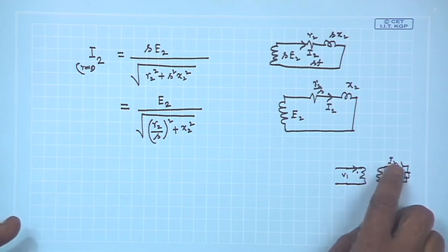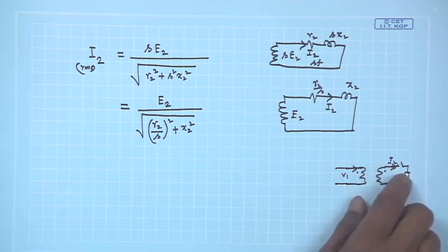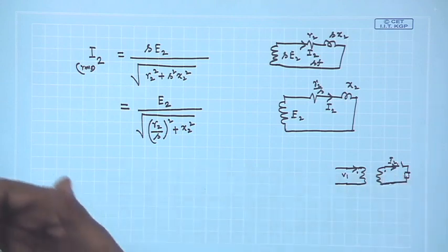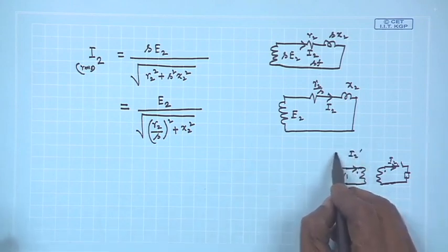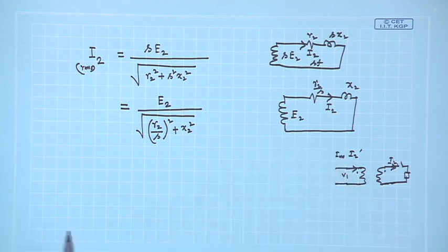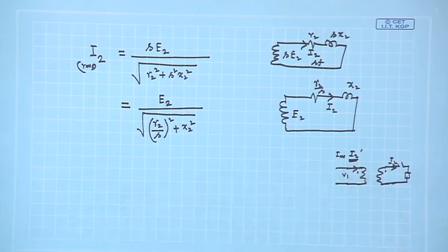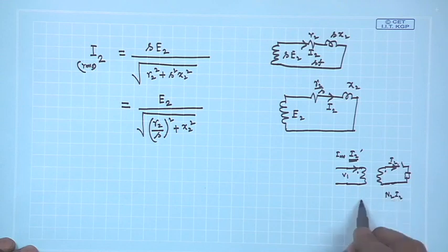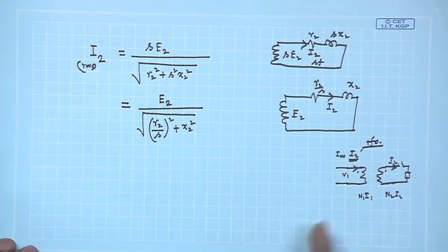Therefore, the extra MMF which is now brought into this system, because you have connected a load on the secondary side, the primary cannot but draw additional current called reflected current, apart from the magnetizing current, whatever it was drawing. And the value of this I2 dash will be such that N2 I2 is equal to N1 I1. It is in relation to a transformer, I am telling.